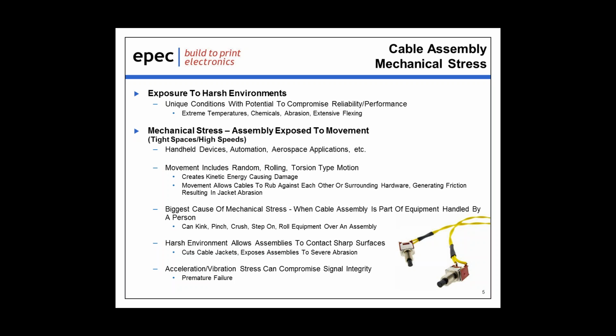One of the biggest causes of mechanical stress is when an assembly is actually handled by a person. People inflict damage to assemblies all the time by kinking them, pinching them between objects, stepping on them, rolling over them with chairs or fork trucks or other equipment. Jackets need to be rugged enough to be able to withstand being pulled over, sometimes sharp surfaces, without failure, if that's the environment the assembly is installed in.